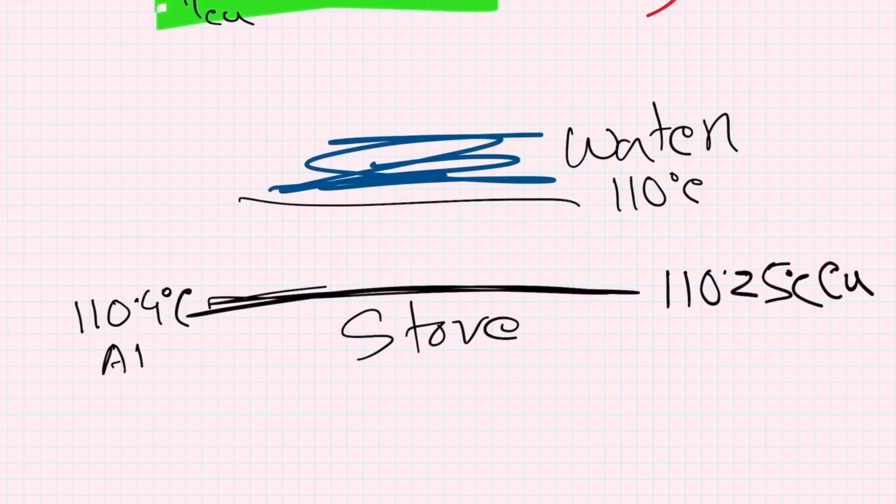When you are using a highly thermally conductive material, heat is transferred quite well, so you can maintain a smaller temperature difference between these two surfaces. The delta T can be smaller and you can still transfer 600 watts of heat. But if the material, aluminum, is less conductive thermally, the temperature difference has to be larger.